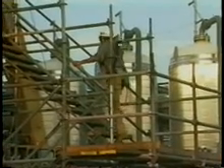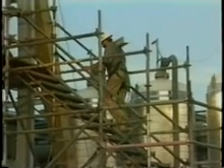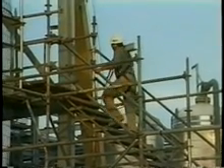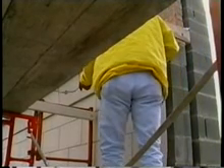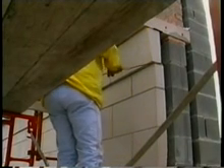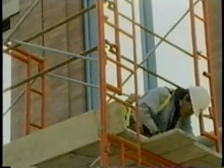When the platform is more than 2 feet above or below a point of access, there must be a ramp or walkway or direct access from another scaffold, structure, personnel hoist, or similar surface. On suspension scaffolds, the competent person must check the scaffold support devices, tiebacks, hoisting equipment, and connections for proper strength and to prevent sway.